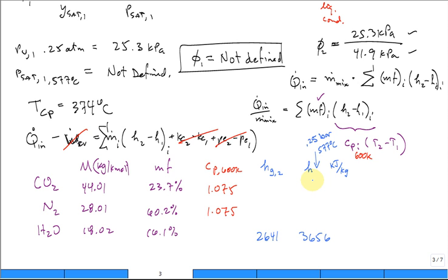So when I put a g there, that's a misnomer, right? It's just the enthalpy of the vapor at the superheated state of the temperature and pressure. It's partial pressure and its temperature. This one, h_g of 2, is the enthalpy of saturated vapor at that temperature of 77 degrees C. Well, so those are all the pieces of the puzzle.